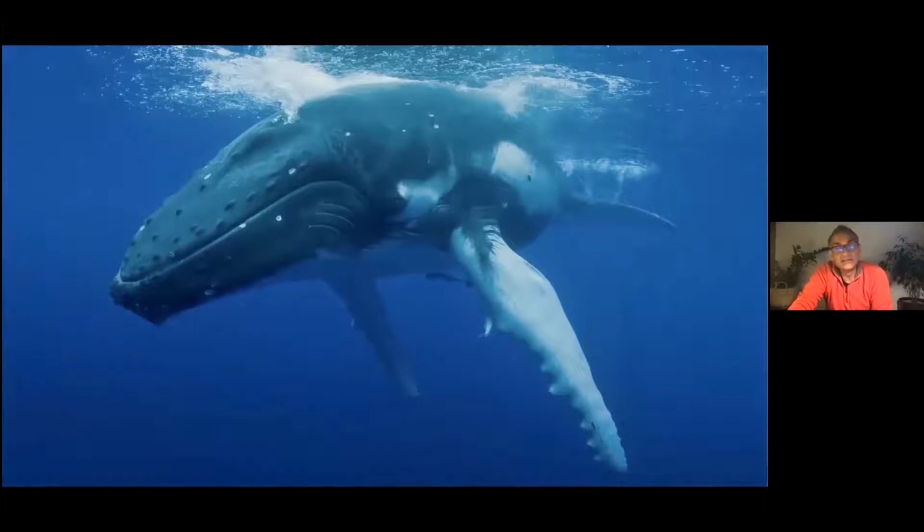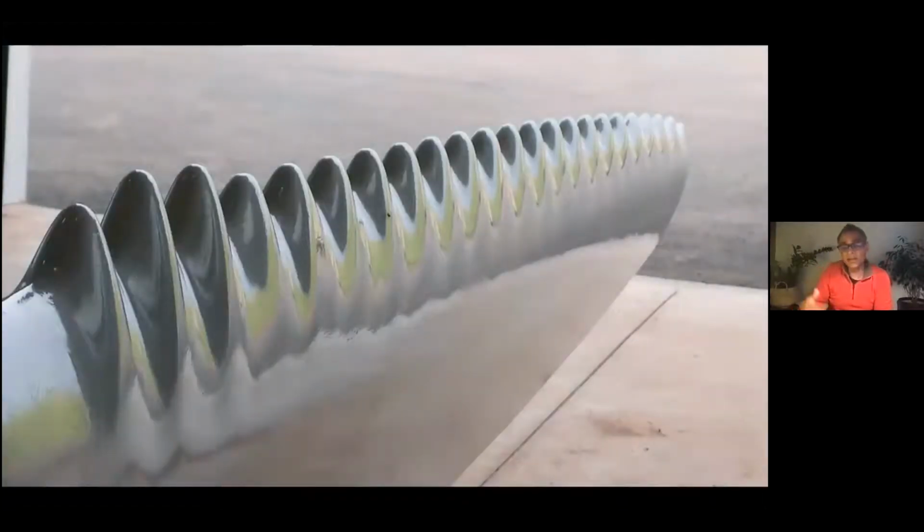One other example is the humpback whale. In this photograph, if you look at the white pectoral fin, you see these little tubercles, these really bumpy regions on the pectoral fin, and that apparently has several really interesting purposes. And this is a wind turbine, which is inspired by the shape of the tubercles on the humpback whale's pectoral fin. What they've discovered is that if you create this sort of a surface on the leading edge of the fin, it prevents stalling, which can happen very often in wind turbines. It creates more efficient flow. Even if the wind speed is not too high, it can still rotate and generate a certain amount of energy.